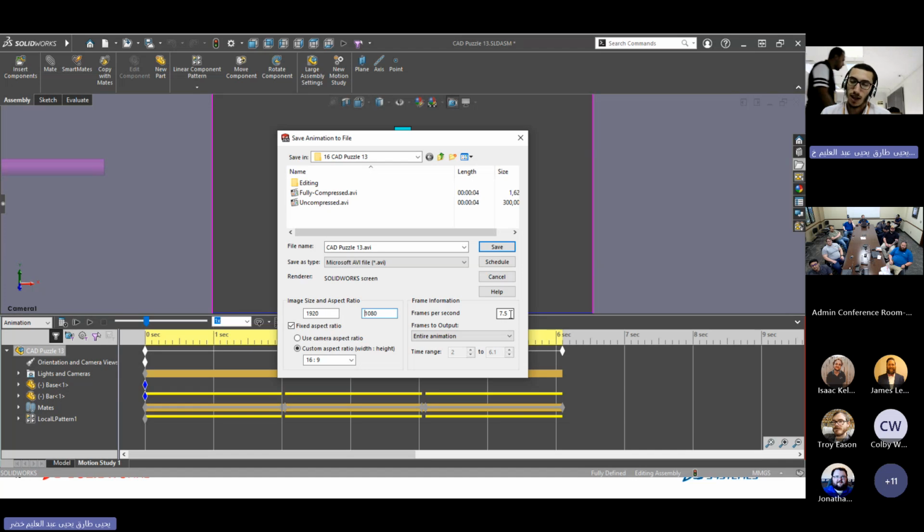Now frames per second. I sat down with R&D of SolidWorks twice, physically sat down with them to talk about this 7.5 value, because this is the worst thing ever. It would really get out the worst video that you can ever see. And I mean, you can go with 24. You can go with 30. You can even go with 60. Actually, a couple of weeks ago, I realized that the film industry in America uses a very strange 27.78 frames per second value. You can use that, but please don't use 7.5 because that's very, very low. And you're going to notice that in your exported videos.